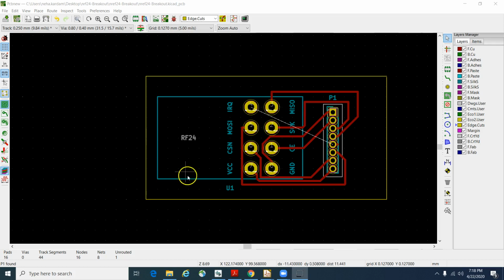So here in this footprint schematic, you might have noticed that the edge cut which I have used here is of a different color. I just wanted to make a little correction from my previous lecture: in the last lecture I think I used silk screen. We were not supposed to use that. You need to click on edge cuts.